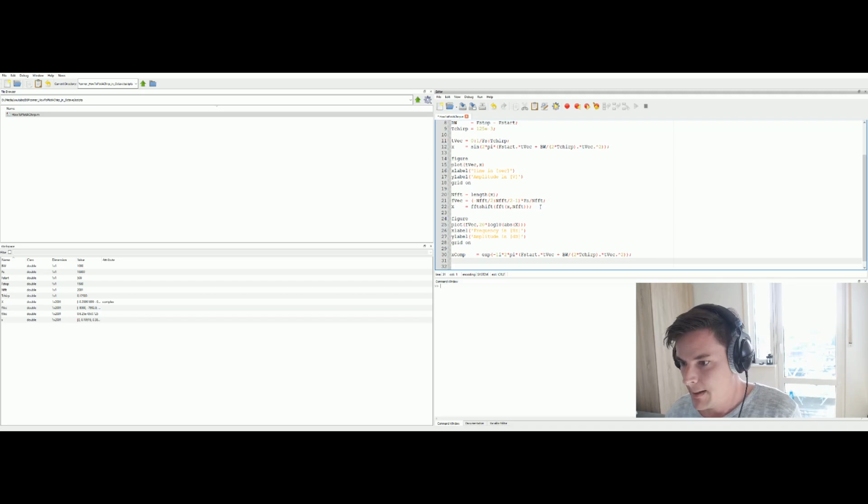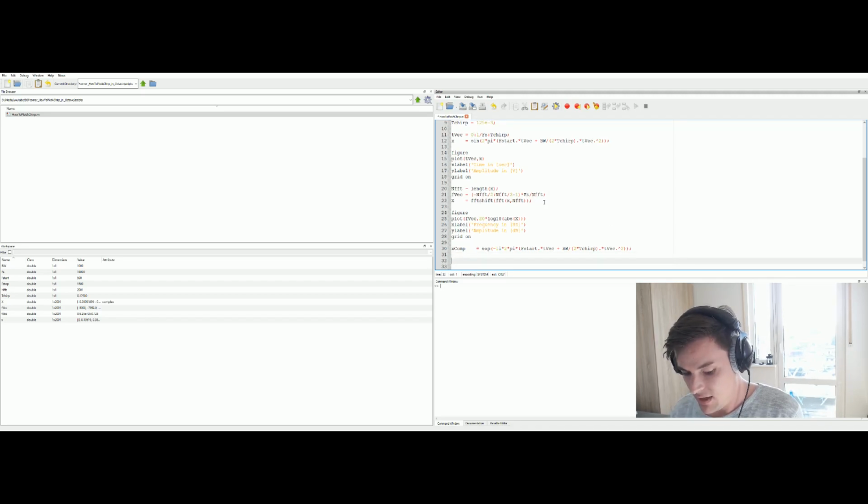So now we can again calculate our FFT. We have the same FFT length, we can use the same frequency domain vector. We only have to calculate our FFT again and we call it this time X comp for complex. So we pass our time domain signal X comp to our FFT command and tell the FFT the length that we want.